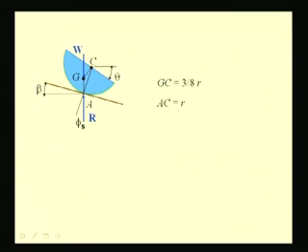So, this picture shows the free body diagram of the hemisphere, the weight of the hemisphere passing through its CG and the resultant of the normal reaction and the frictional force passing through the point of contact A, which is lying just beneath G. From this geometry we know this GC, which is nothing but the location of the center of mass, which is equal to 3/8 times r from the diametrical plane, and this distance AC is nothing but the radius of the hemisphere.